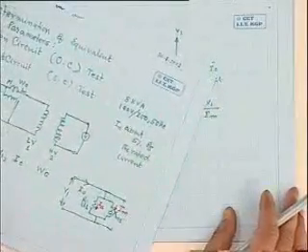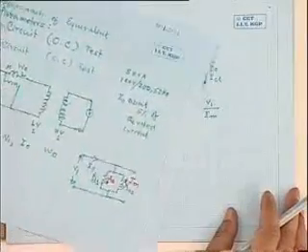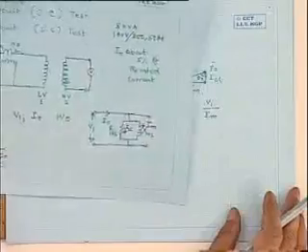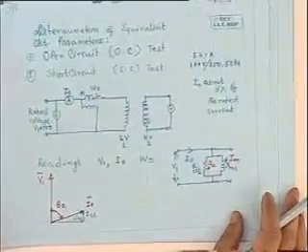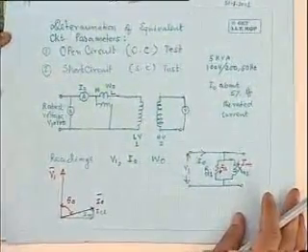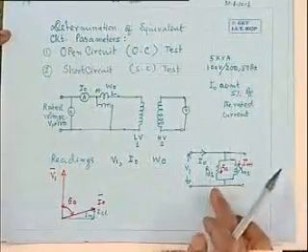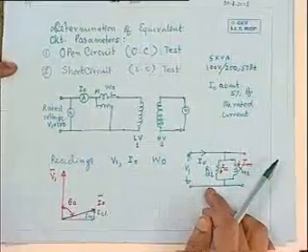the ratings of the wattmeters, pressure coil of the wattmeter, voltmeter, etc. will also go up. So generally, from the LV side, the open circuit test is carried out, and RCL and XM is calculated with respect to that side.